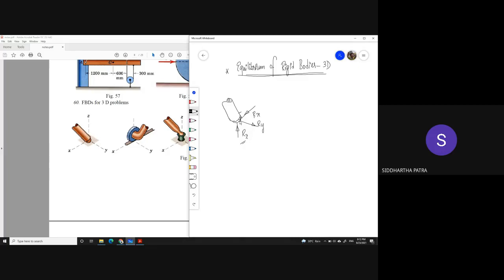But then you also come to know that the surface is rough. Then you would be getting reactions in Rx and Ry. That means the surface doesn't let the object slide in X or Y. But the surface being spherical in nature, there is no restriction over rotation. I hope you can understand that. That means with respect to its spherical end, the rigid body itself can perform rotation about any axis.